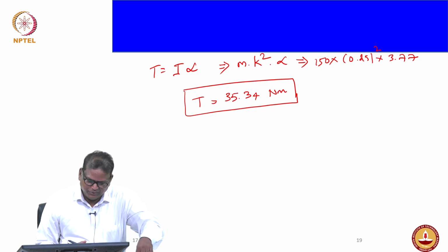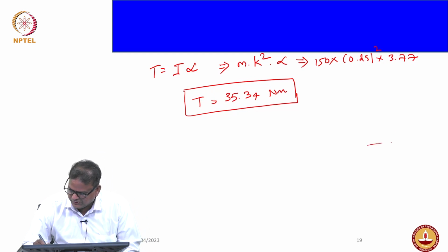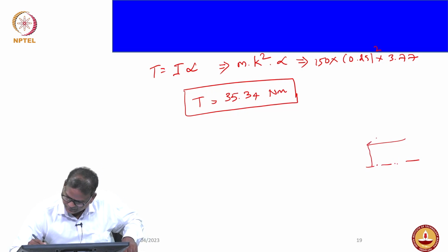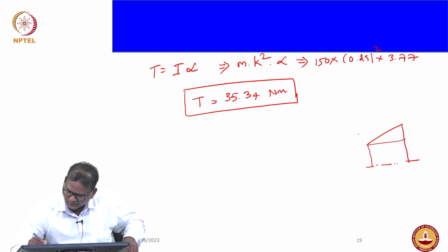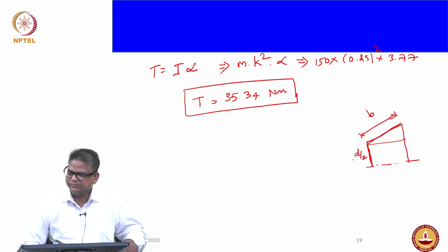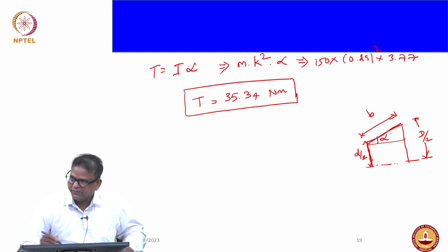Before using the uniform wear theory, consider the relationship given. Let me draw it. I am showing only half of the clutch. This is the face width, assuming this is the face width. This would be my inner diameter, the cone. This will be d by 2, and this would be capital D by 2. That is the information, and alpha is given.